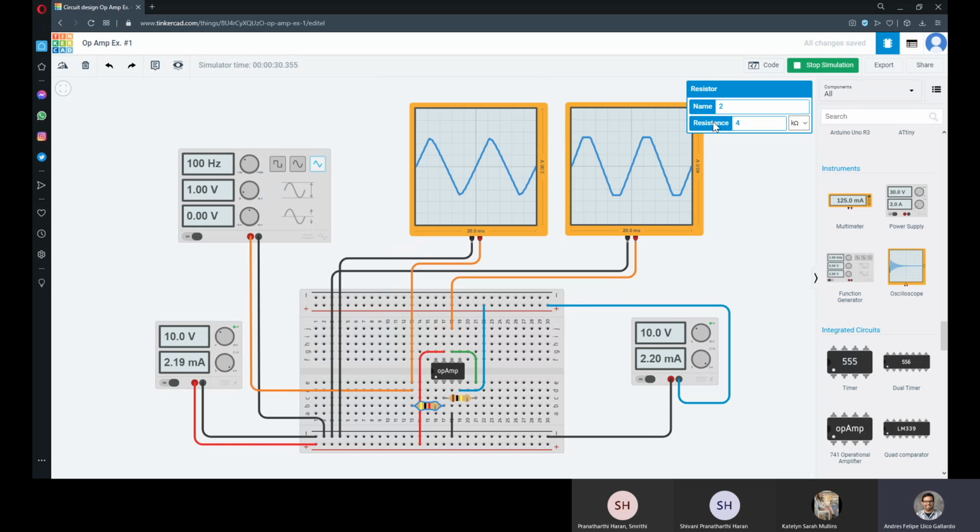Okay, now we start seeing something interesting. I'm actually going to change to 3. Okay, so as we keep decreasing the resistance here, we know that the amplification is given by the ratio between the resistors. So now the ratio is 100/3. That's 33.3. So that means that the amplification of my signal, which originally was 1 volt, so that volt now is amplified 33 times.